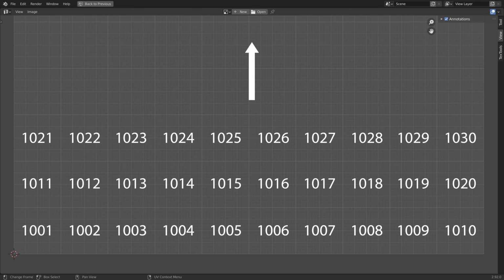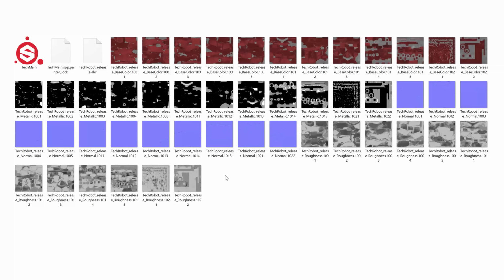These numbers not only help us get around in UV space, but they are also used to determine where image textures belong by looking for each number in the name of the files. So anytime you have a bunch of UDIM textures, you will find their tile number somewhere in the name, so they can be loaded as a sequence and properly placed in the correct tile.